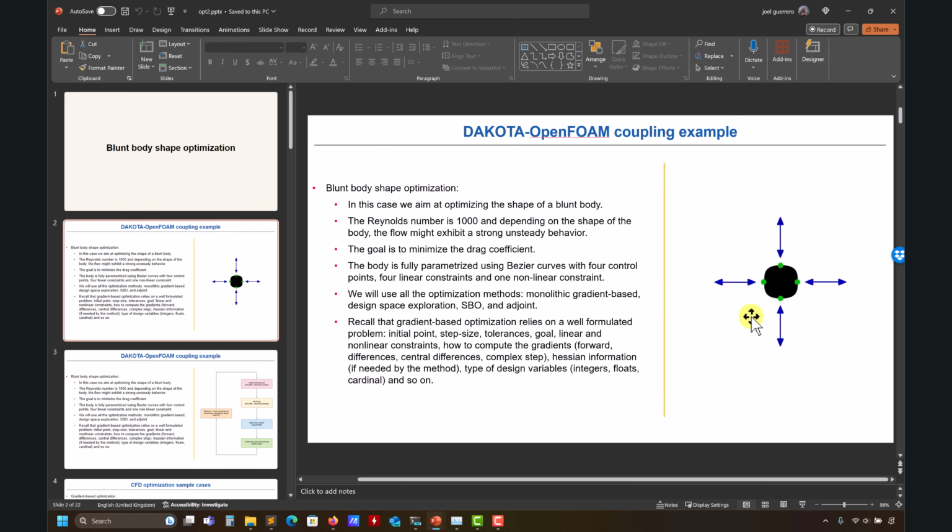But everything that we did was single objective. In this video, we're going to do multi-objective optimization. That is, we want to minimize drag and maximize lift and whatever. Okay, you can have it in many combinations. But this is our goal. And when we do this, things change a little bit. So we cannot use gradient-based method, or better to rephrase that, yes, you can use, but it's not the most efficient way. You need to use specific methods that are formulated for this kind of multi-objective optimization problems.